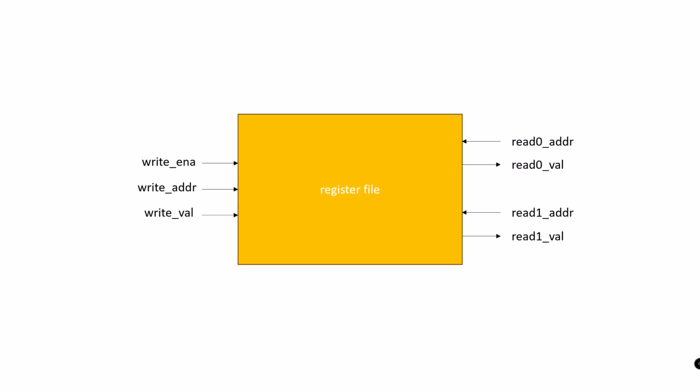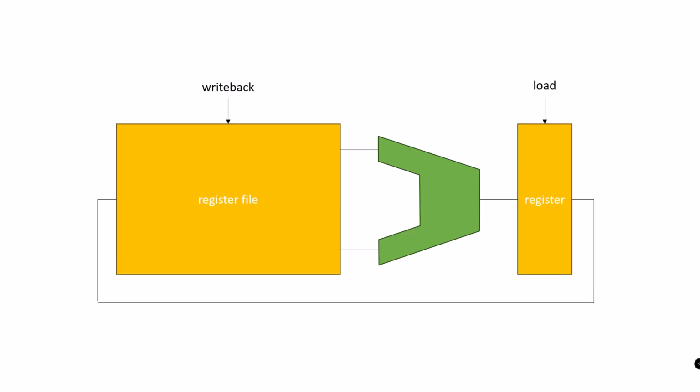The register file uses a specialized circuit based on static RAM to provide both speed and compactness. We can't read all of the values in the register file at the same time. We use ports for parallel access to more than one word. For example, we can provide 2 read ports that can be operated in parallel. We can also use a write port to write a value back to the register file. We add the temporary register to the data path to avoid combinational cycles if we tried to write directly from the ALU back into the register file.